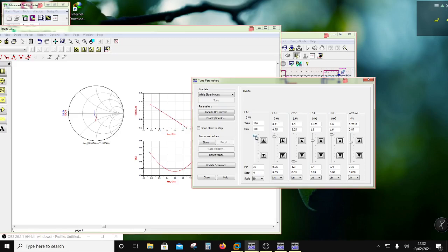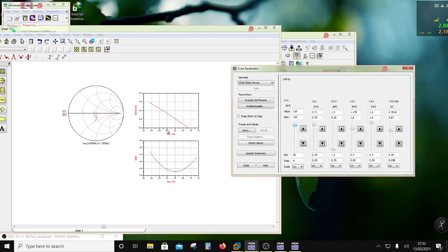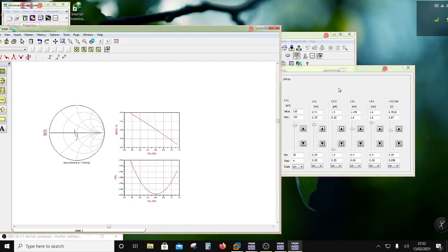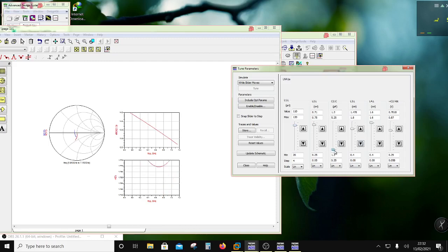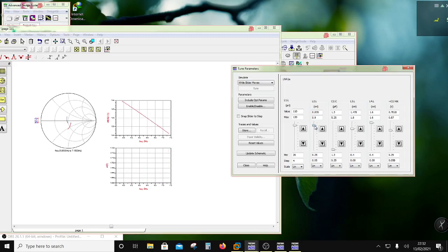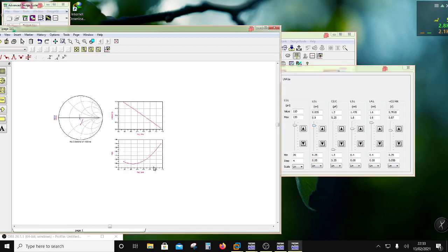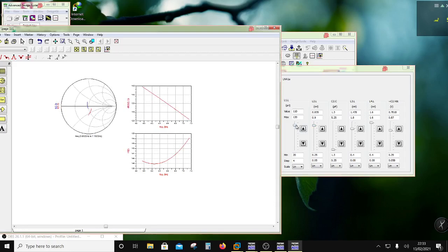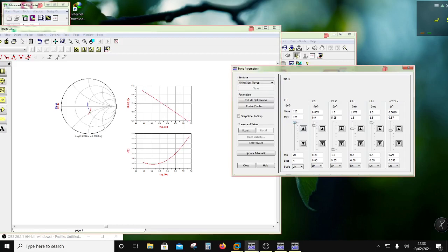And let's see if it can be dropped further. So right now the gain is between 12 and 14, and the noise figure is 1.77 something, right? So this is 0.9. Okay, so let's see what has happened to the noise figure. It's around 1.7 something. Okay, 1.6 something. And so I'm working with the match and the noise figure, correct?